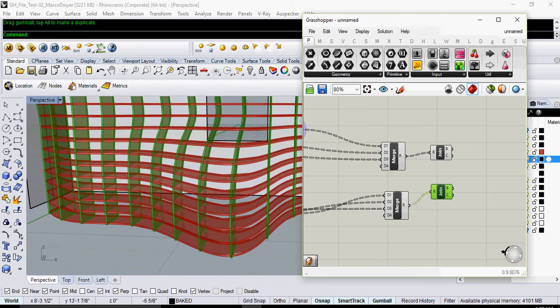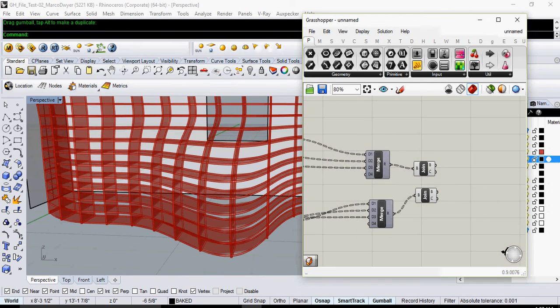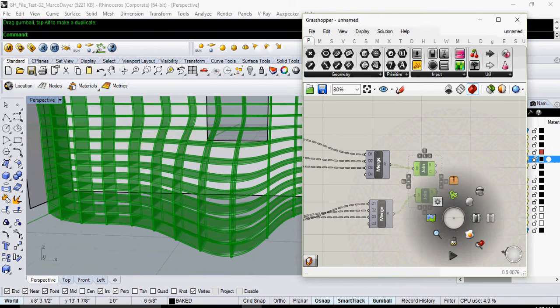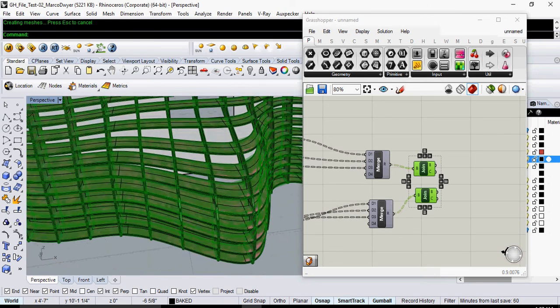And I'm going to take these out of Grasshopper now, like this. So I'm going to select these, and you can right click, bake, and put them in the correct layer, which would be the right thing to do. But for now, I'm just going to bake them really quickly by just test baking. I'm going to actually delete them after I'm done.